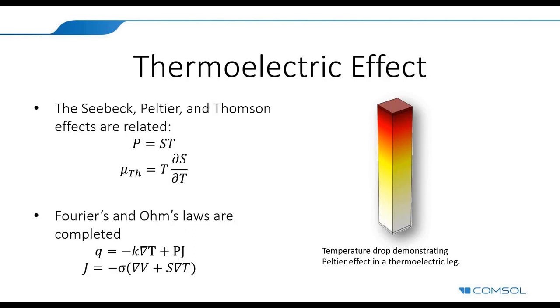And the thermoelectric effects gathered all together are related by some expressions that introduce some coefficients, the S coefficient here, from which we can define the P coefficient and the mu coefficients. And thanks to these definitions, we can redefine the heat flux and the electric current so that we account for the thermoelectric effect. So you remember that I introduced the heat flux from the Fourier law, and here we can